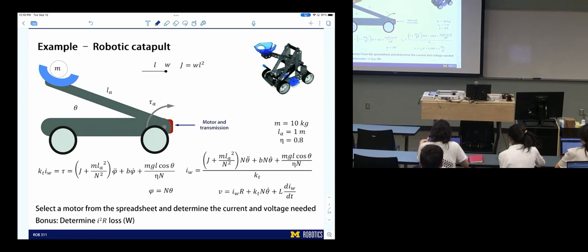Step 2, try to determine how many components of torque there will be. So like we know inertia will be there, loss will often be there, and then in this case, there's a gravitational component of load. It has to do with the kind of weight of that arm. So once we understand there's going to be inertia, there's going to be loss, there's going to be some weight of that system, then how do we represent that? Hopefully you could go from those thoughts to these expressions.